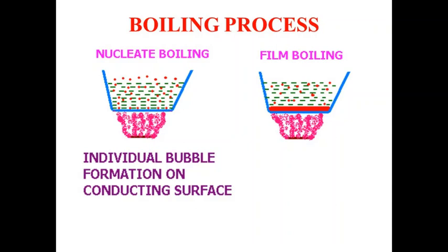When we continue to add more heat, the rate of heat transfer increases. Gradually some liquid particles get overheated, attaining more than the sensible heat gain, and they receive the heat available in the vicinity, and with this excess heat they receive the latent heat of vaporization and turn into tiny vapors.